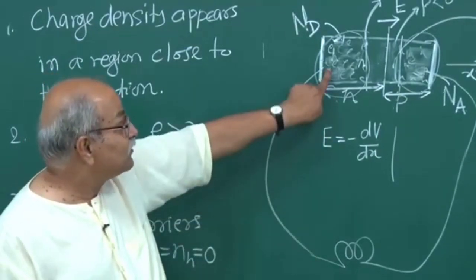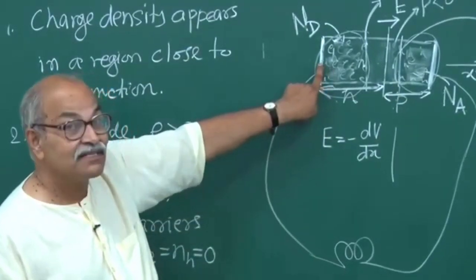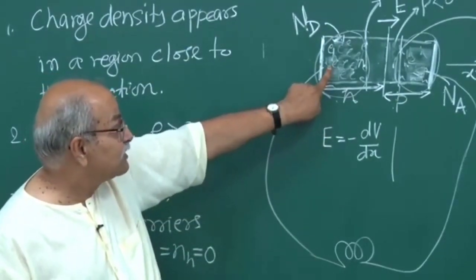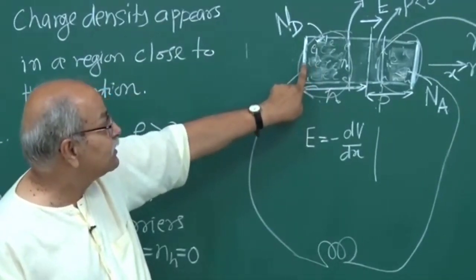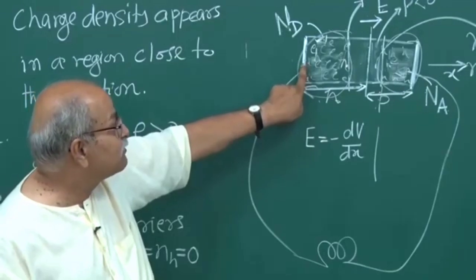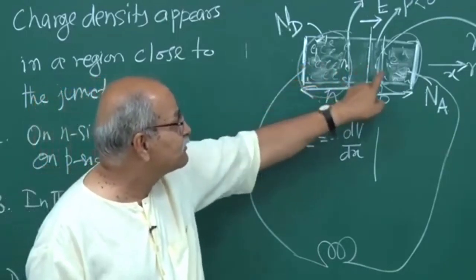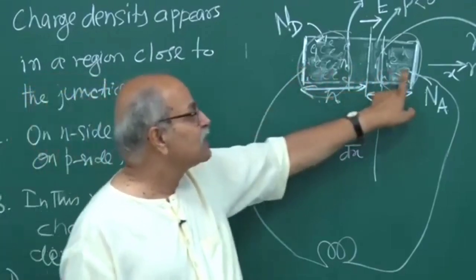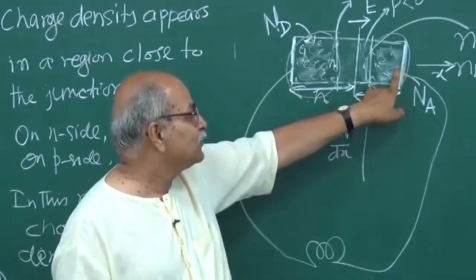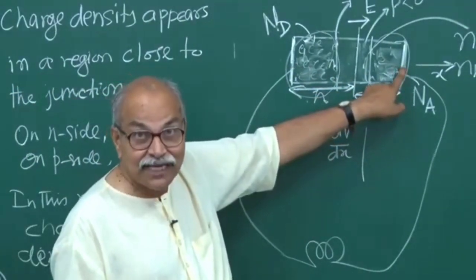Because here also you have different kinds of materials. You have the doped semiconductor here, and then you have the metal here. Once you go from a semiconductor to a metal, there is a junction out here, so you do have a potential difference here also. As you have a potential difference across this junction, you also have one across this junction, and similarly across this junction. So here also, semiconductor to metal, there will be a contact potential difference.